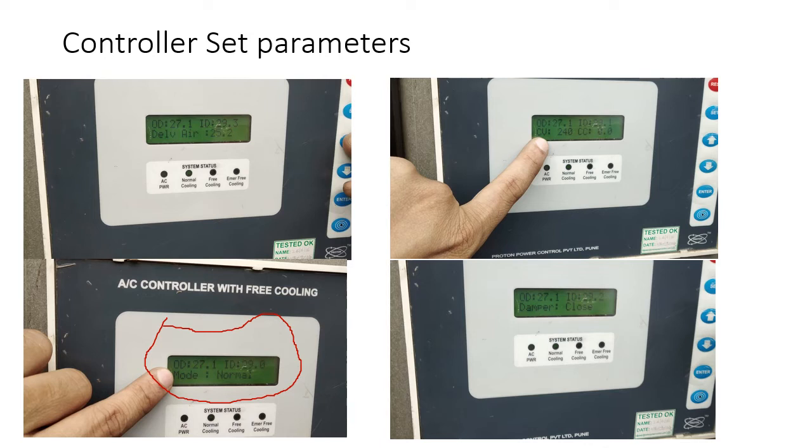If you look at the bottom line, you see the compressor voltage, and CC is the compressor current. Here it is shown as 0 ampere, that means the compressor is in off condition. In this picture you will see the damper position. The damper is closed, that means free cooling mode is not activated.